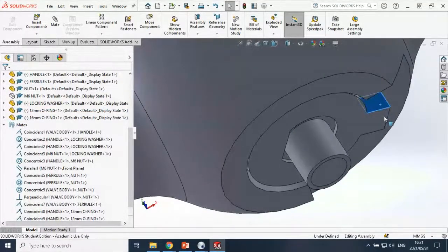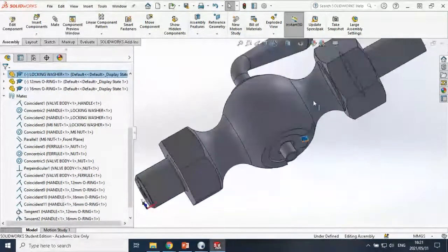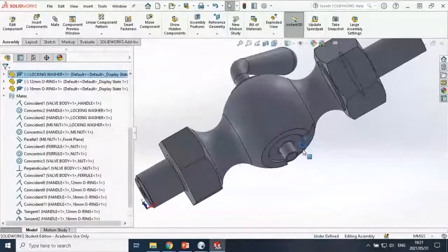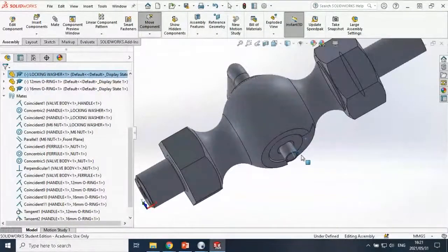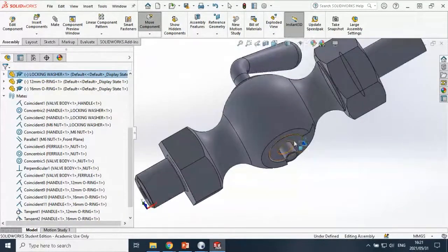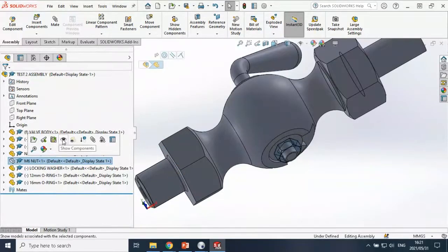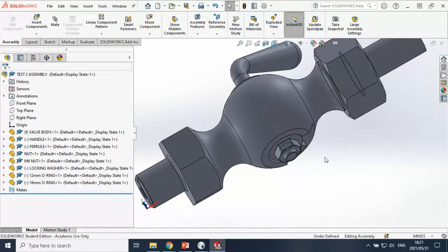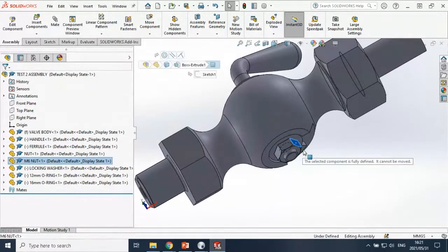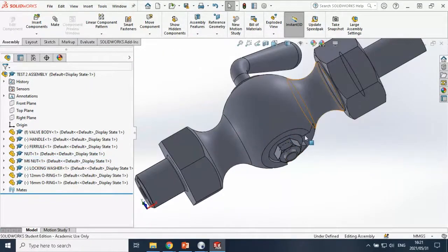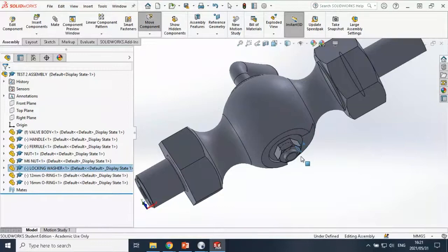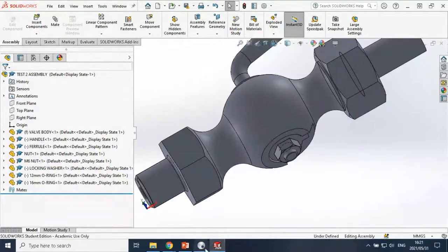Okay, so if I turn the shaft, the washer will turn as well. Meaning the thread is not affected by the turn of the handle, because everything at the bottom there, including the nut, is forced to turn together. Okay, I'll just have to add a mate for that nut, because at the moment the way I set up the assembly, it's going to stand still. Okay.